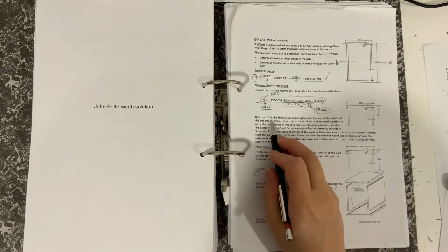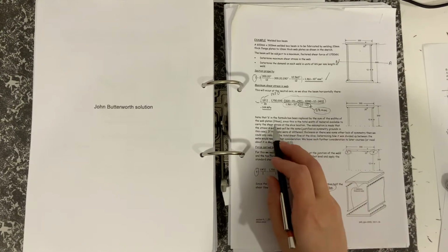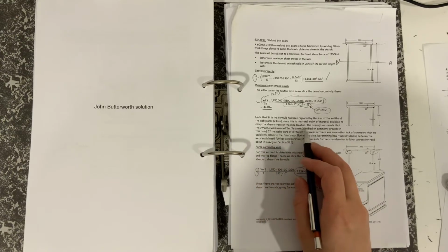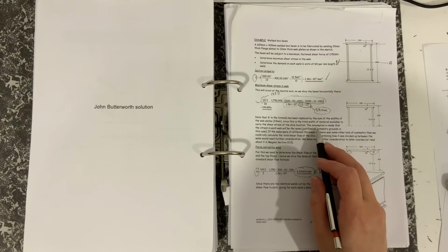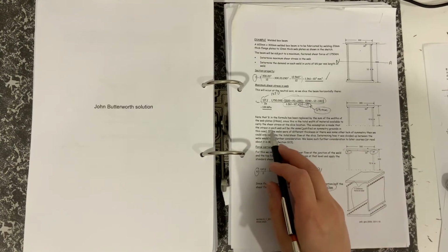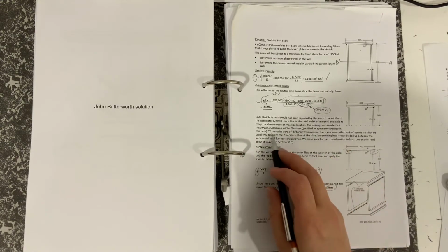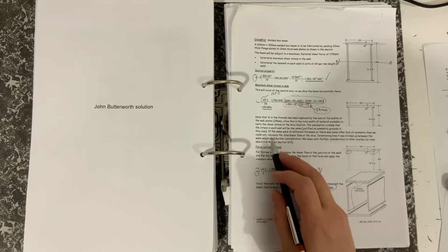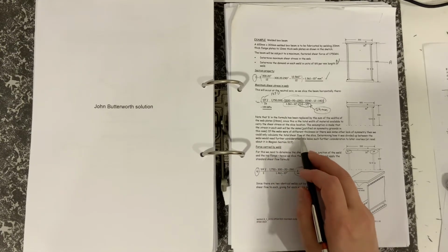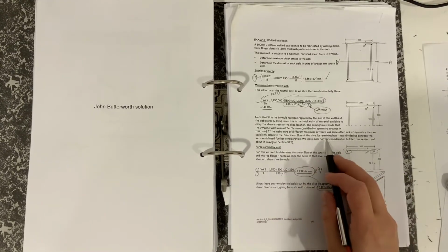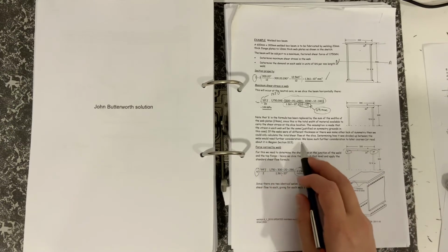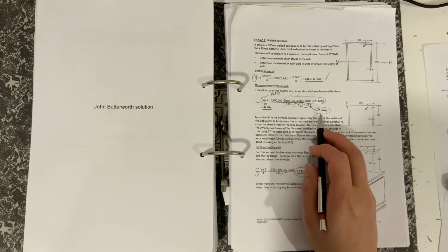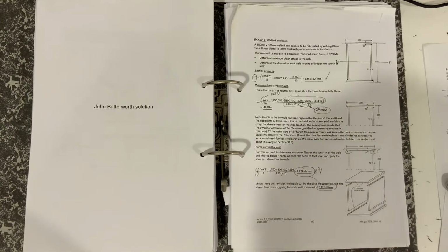Note that b in the formula has been replaced by the sum of the widths, since this is the total width of the material available to carry the shear stress at the slice location. The assumption is made that the stress in each web would be the same, justified by symmetry. If the webs were of different thickness, or if there was some other asymmetry, then we could only calculate the total shear flow at the slice. Determining how it was divided between the webs would need some further consideration. Because they're both the same, you can add them together for the reasons I've just described.